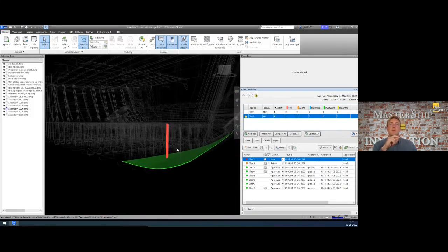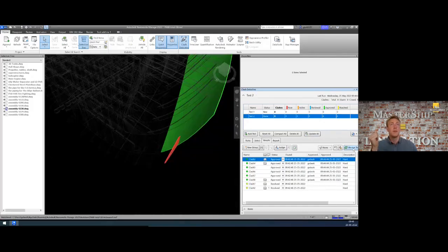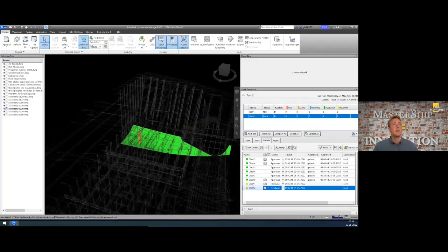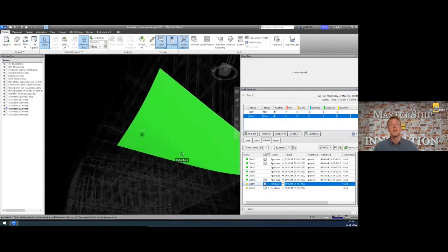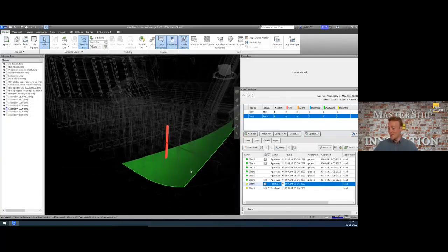And if we now look at our clash again, so here this was the clash, and this was also the clash. We do our test again. So we rerun the test, and there we see it. Clash 1 and Clash 2 are both resolved. So that's automatically identified. We can take a look at it, but we can also just say, hey, they are indeed resolved. So we do not see it poking through the hull plate anymore. So we are happy. So this was now an example of a collision fix.